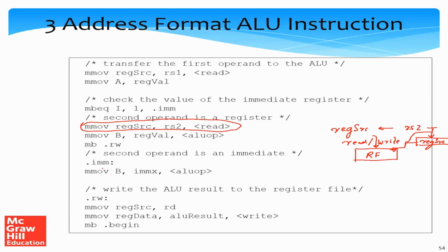So in this case, we save one cycle. So this is an interesting, neat, elegant, efficient optimization to make. We do the same thing for an ALU operation as well, where we also write the value of regval to micro register B and also simultaneously initiate an ALU operation. So this can be done, and with a small forwarding path, this can be done. So this is per se not a very technically challenging operation.